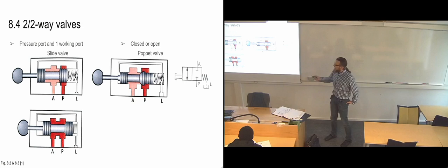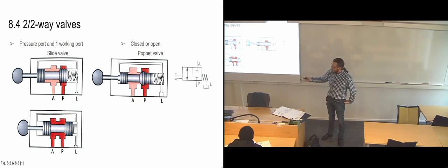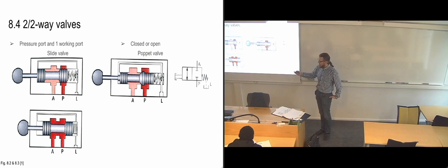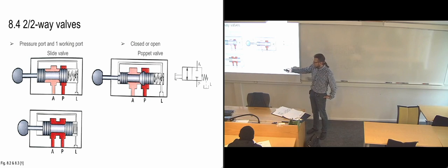So for the slide valve, when we are opening it up, we are pushing in the slide, so then we get full flow between the P and A ports. And now you can really see that we are going to end up getting some leakage over here on this side. And most likely what little leakage we do get when we have activated this one, that's just going to stay in this chamber while it's running, so long as we are actuating it. But as soon as we let go of this lever and the piston starts moving this one back, then you can see here it's going to go completely flush with the edge there. And then it's just going to force everything over on this side.